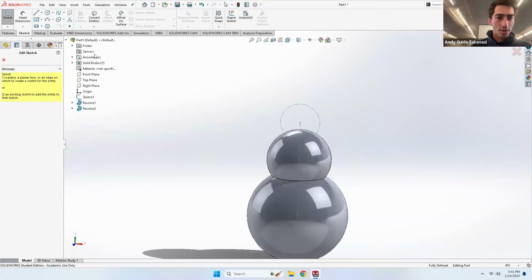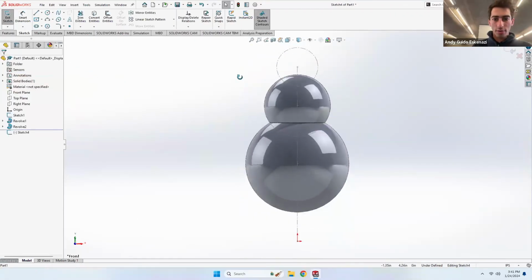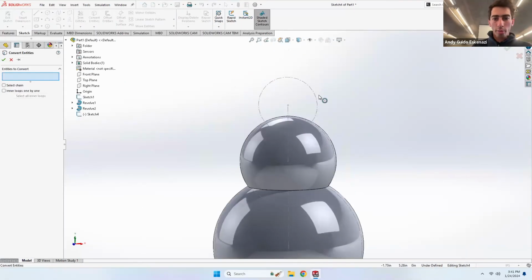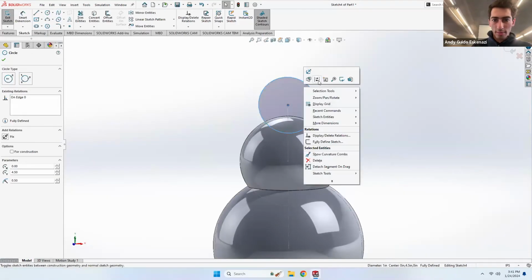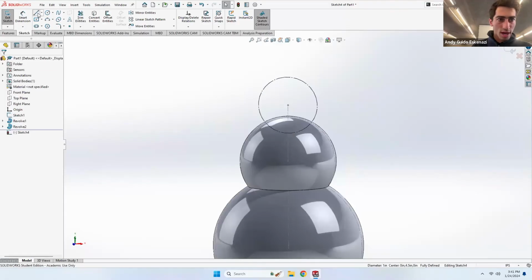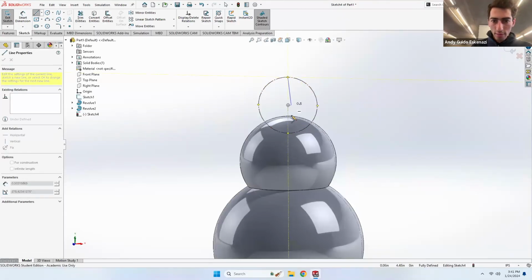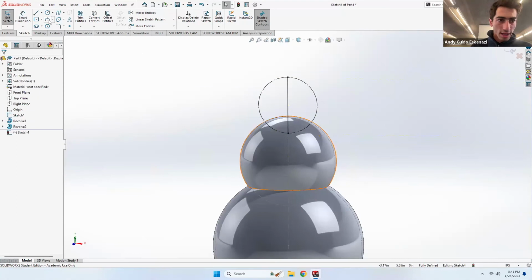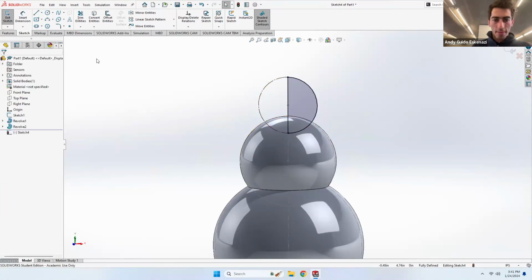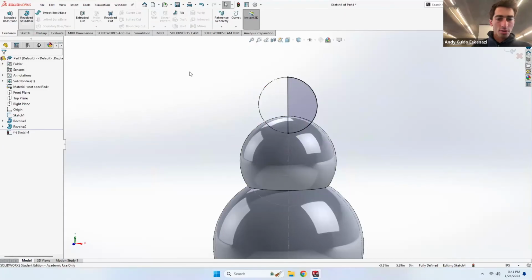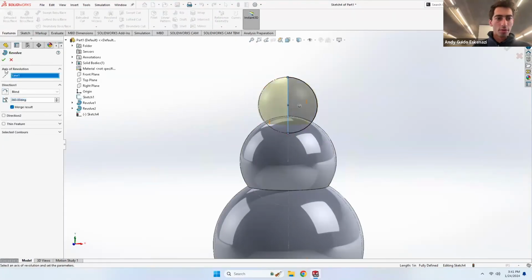And then I'm gonna do one last time in there. So sketch on the front plane. I'm gonna convert entities. Then I'm gonna make this become a reference line, draw a straight line from here to there, and then do a little arc that goes all the way like that. And then features, revolve. I'm gonna revolve in there.